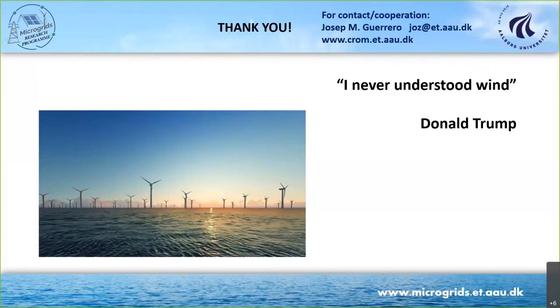Can you discuss more about virtual inertia and how we are going to achieve it? Yes, virtual inertia is one of the more attractive things, especially when you think about offshore wind that has type 4 converters, meaning full-rated converters. Virtual inertia is possible because you have to imagine that your machine is rotating, and then you still have some inertia that you could use to inject extra power to the grid.